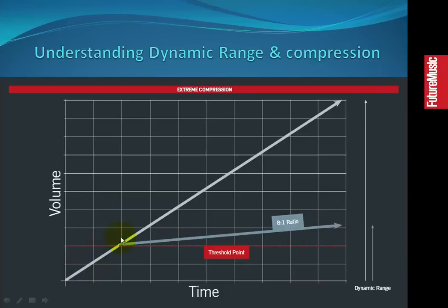That means anything that is louder than, say, a whisper will be affected by compression of this ratio, 8:1, which is quite a high compression ratio. So anything louder than a whisper will be compressed by quite a lot. As a result, we can see here this slightly darker blue line. The dynamic range of this particular conversation, this theoretical conversation that we're talking about, has been greatly reduced.